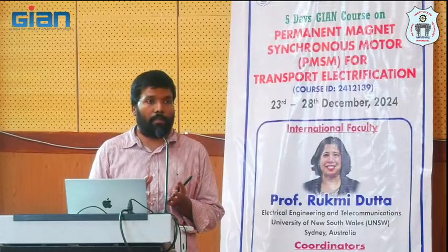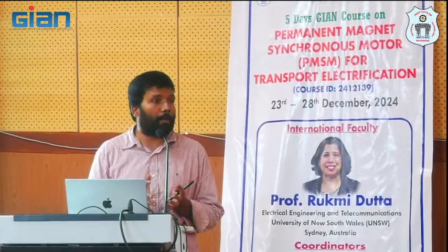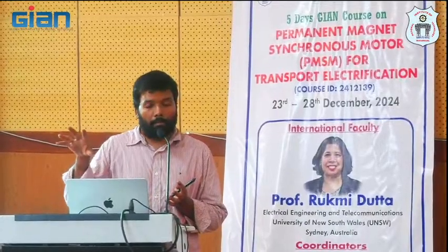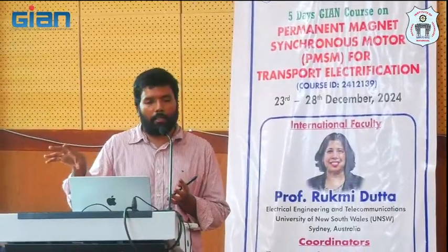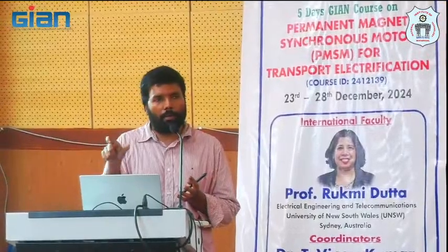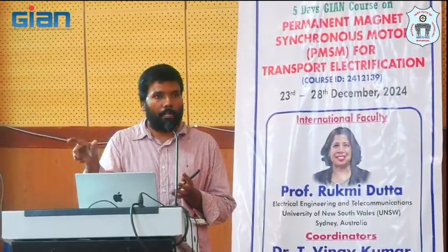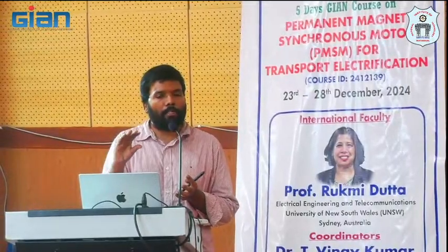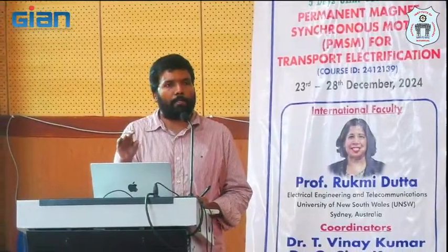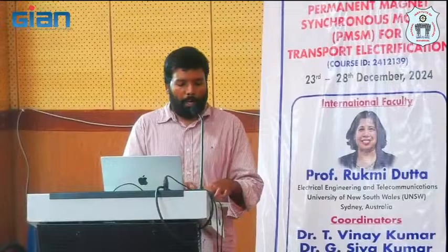even if you give a reference speed of 1000 RPM, with respect to the duty period, your duty will not operate at 100%. Your duty will operate at only 10% of the rated value. So initially only 10% voltage will apply, and frequency will also be only 10%. Because of this, what will happen? You will get automatic self-starting.